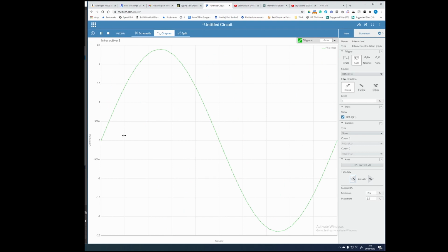So current flowing in the circuit. You see on one side of the wave here, because we're only going from 0 to the peak value, it is 2.4. We're not seeing quite the top there because it says 2.39, but it is going right up to the top there. So we've got the current we thought from our calculation.